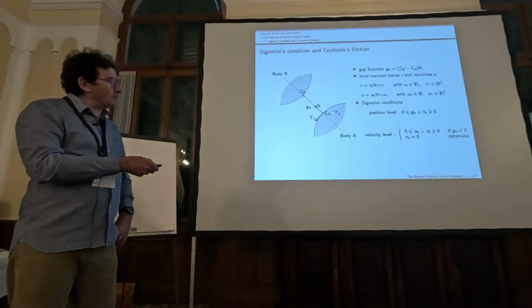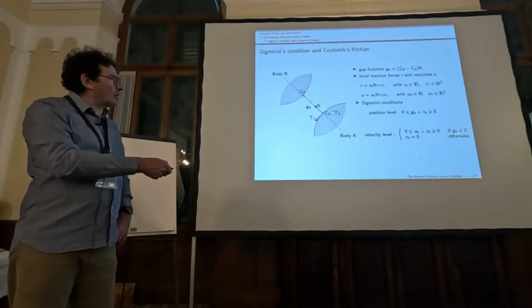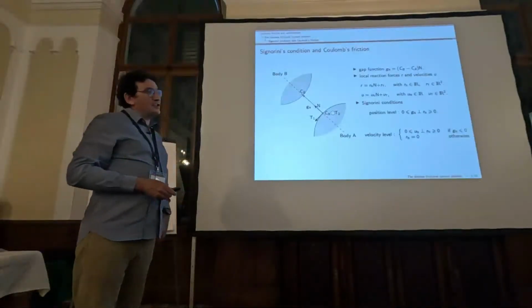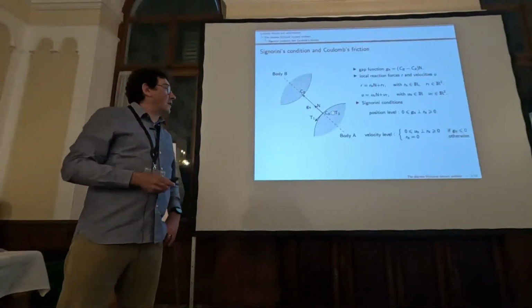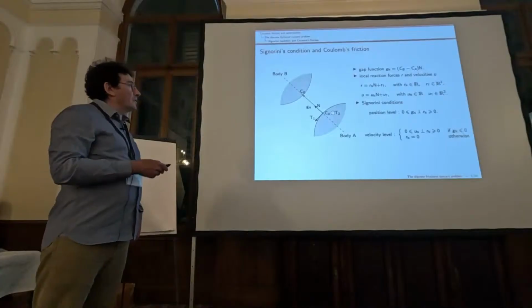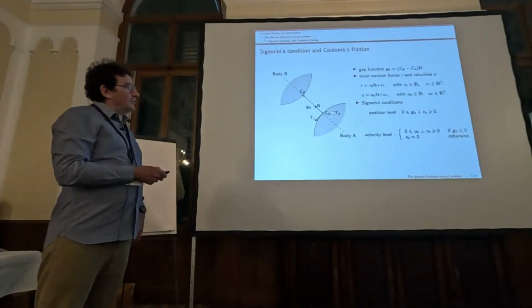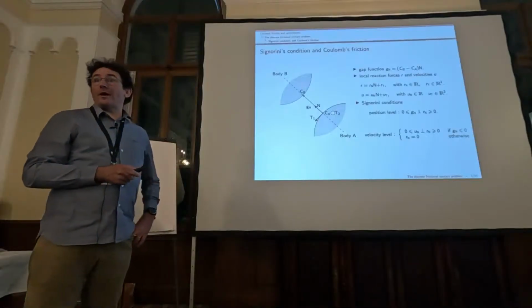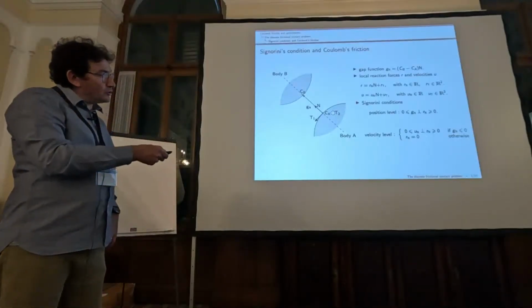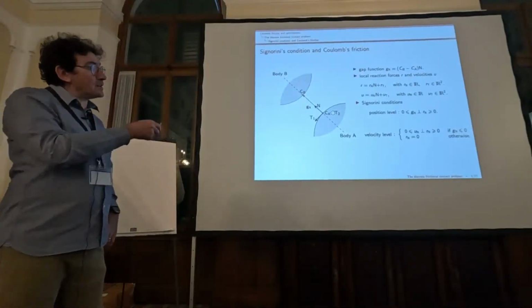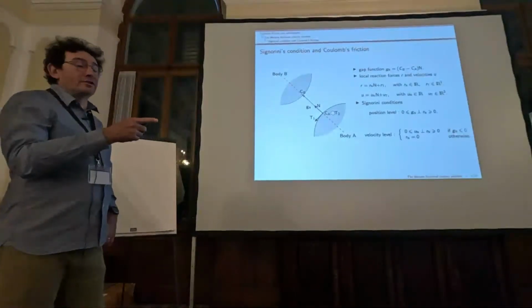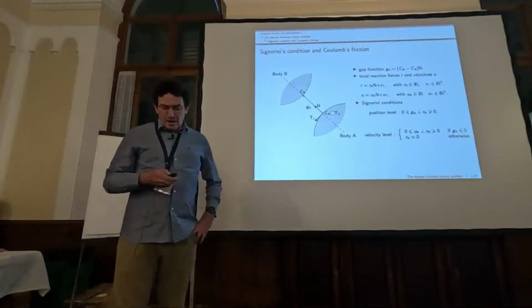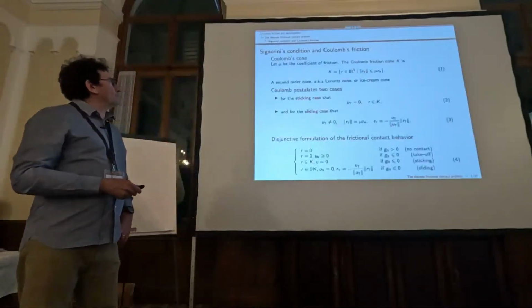The meaning of this perpendicular sign, sorry for that, I am colorblind so I'm not able to see the pointer, but since it is here, means that Gn times Rn is equal to 0. And I will use this condition at the velocity level, considering un, the normal velocity. So un has to be greater than 0 if we are in contact, and Rn is also greater than 0. And if you are not in contact, Rn is 0.